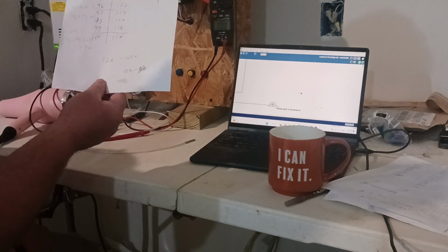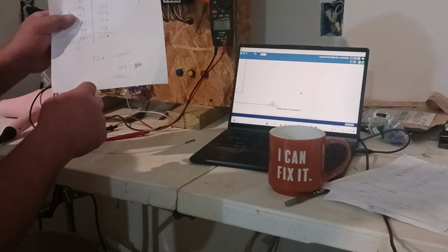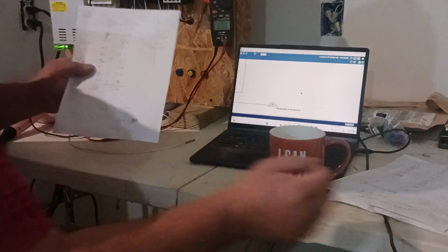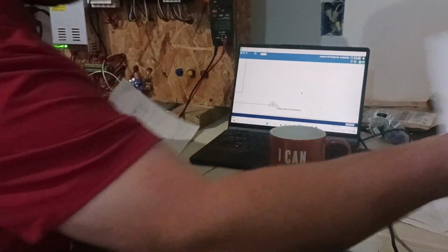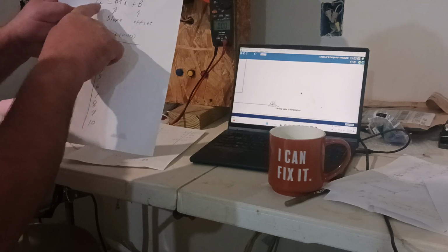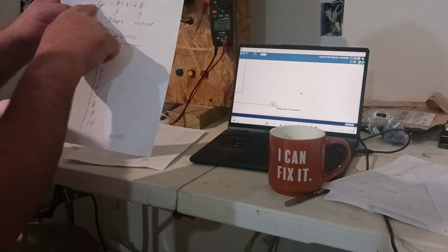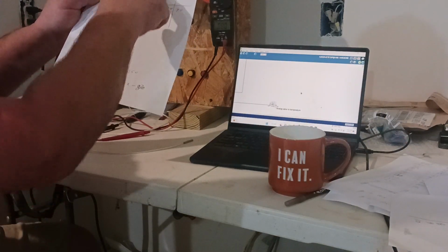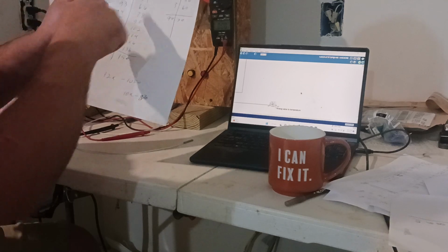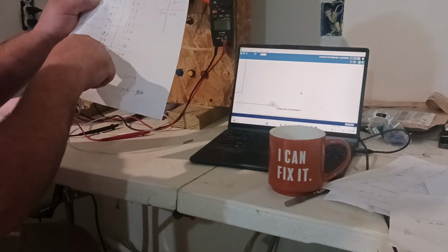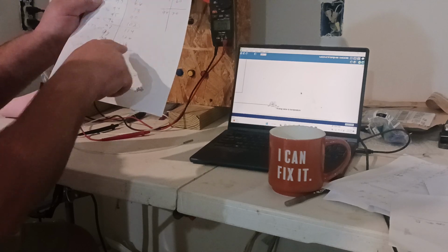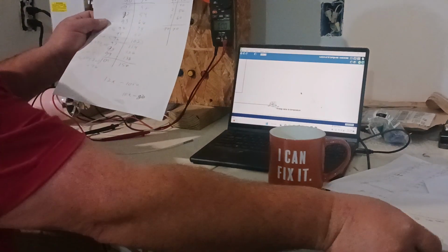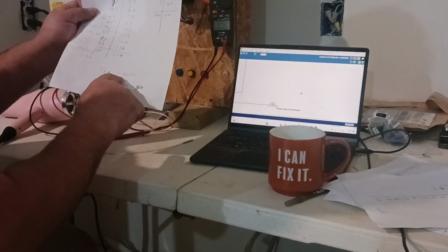So basically what I came up with is my slope, y equals mx plus b, right here. This is our equation for our slope. This is the slope. This is the offset. This is just kind of a linear equation. And I noticed with this value, we change by 12. Every time our analog value increases by 1, this increases by 12. So slope is 12. And when you work the formula, which I'm not going to bore you with all the details, our offset was negative 1050.